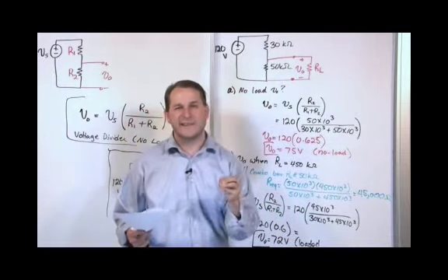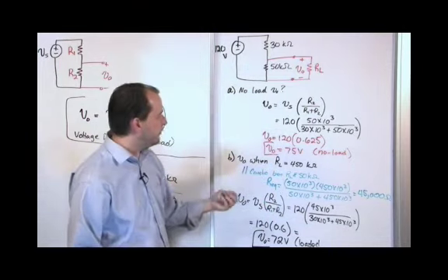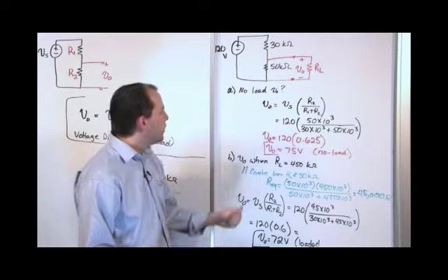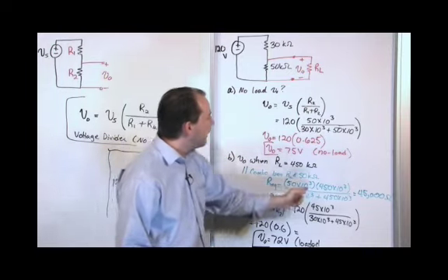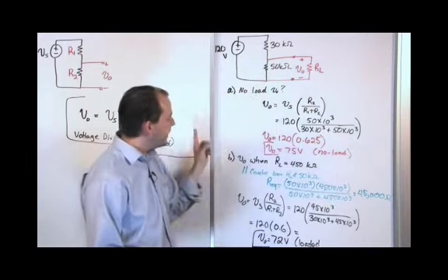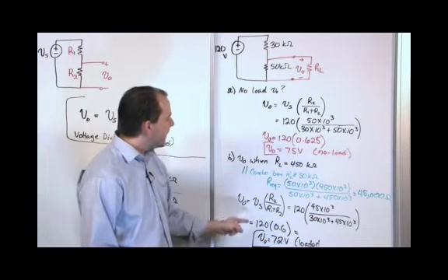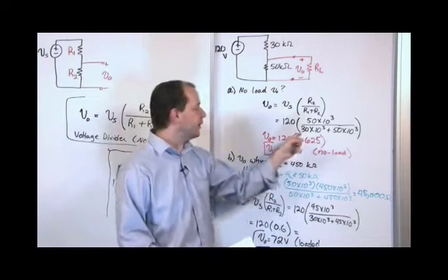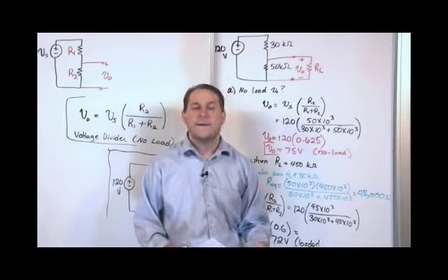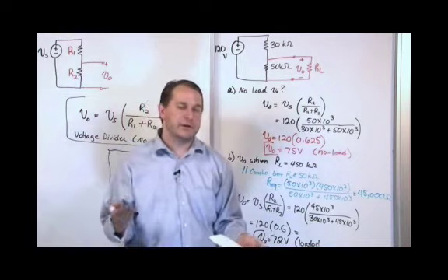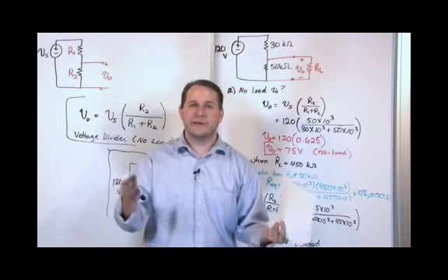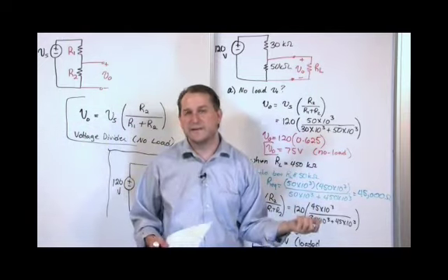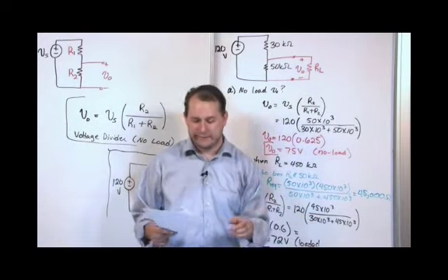But the point of this lesson is to tell you the no load voltage is what you calculate when you don't have anything connected there. You just do the voltage divider law. When you load it down, first you find a parallel combination of what you've hooked up, and then you do the voltage divider again, and the deviation from what you got the first time is going to be more apparent if you choose a low value of your load resistance. It'll be more in line with what you calculate with no load the closer and closer you get to infinity for R sub L. Because when you think about it, if R sub L really becomes infinity, it's like no load at all. So that kind of makes sense.